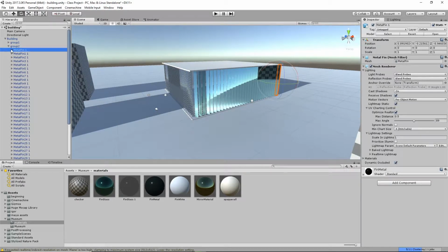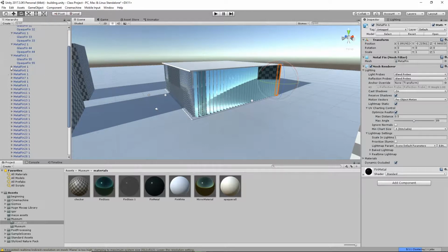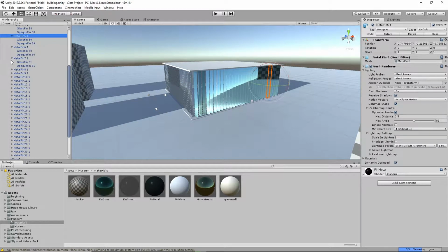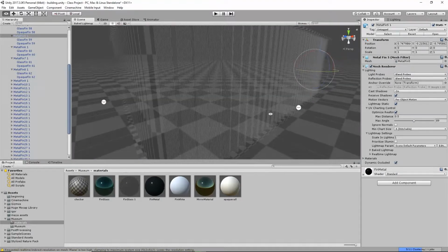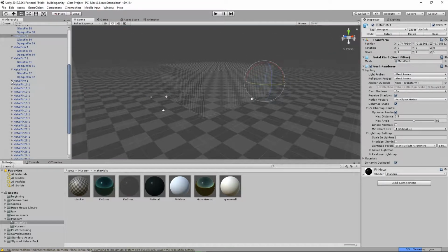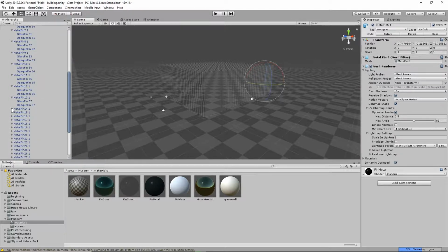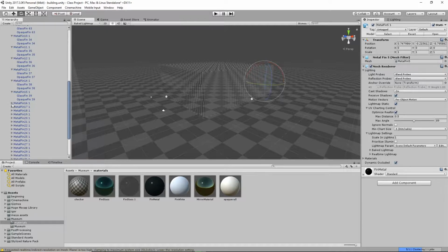So I need to select everything in this secondary, because that's probably what's eating up our render time right now, is all of these are rendering really large light maps. See the scale and light map setting here? That's why it's taking a long time. You can also see that reflected in their baked light map, notice that they're still super fine. So we're going to open these all up and change their scale. Now, this is how you go and optimize your lighting if it's taking too long to bake.